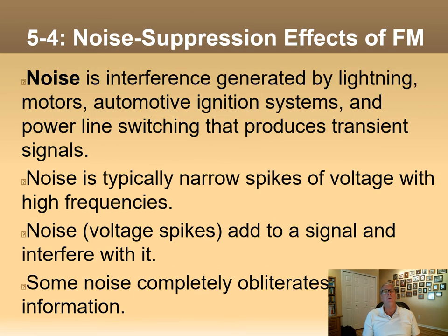So let's talk about noise, one of my favorite subjects. Not really, but I think a lot of my life is taken up by fixing noise problems on circuit boards. So it's an interference that interferes with the signal that you want, generated by lightning, motors, automotive ignition systems, and power line switching, and all sorts of things. It's also generated by your own circuit. So you can get parts of your circuit generating noise into other parts of the circuit. So you can shoot yourself in the foot, so to speak.